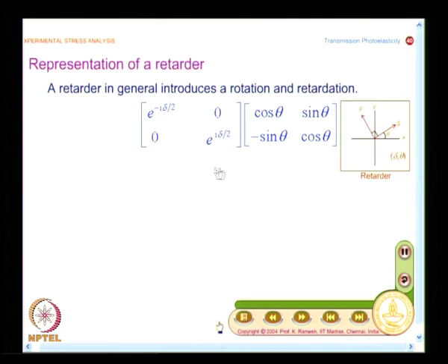So, this definition will have only the crystal plate or model reference axis, but if I have multiple optical elements, it is better that each optical element's output is referred back to the xy axis, then I can repeat the same thing for every optical element. Then you have a simple matrix manipulation that will tell you what is the exit light. In trigonometric resolution, you have to find out how it enters the model, introduces retardation within the model, and then rotate back. All those steps you have to do individually. Now you do not have to do that.